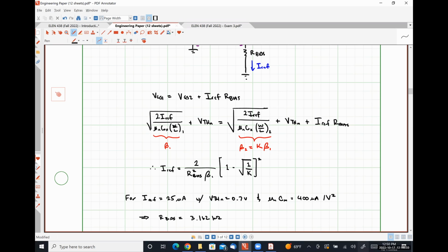So we reduced the size of the biasing resistor needed by a factor of about 52. So it occupies a lot less space. And a change of plus or minus 5 to 10% is not going to be nearly as catastrophic as it would have been with that large resistor. Okay, so we have decreased the size of the resistor needed, which in turn lowers the temperature dependency of this circuit.